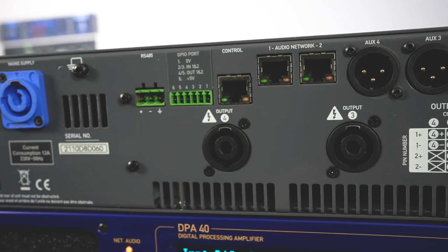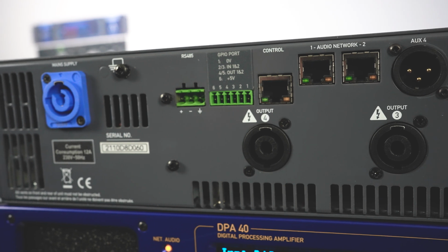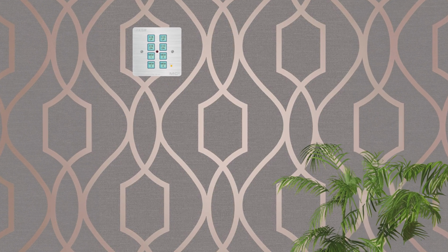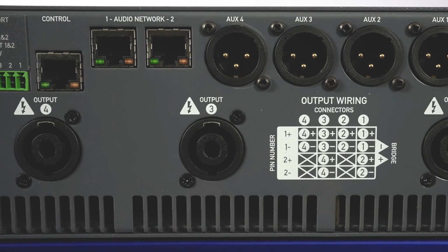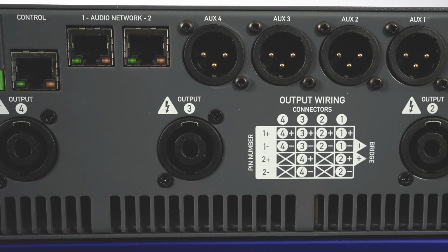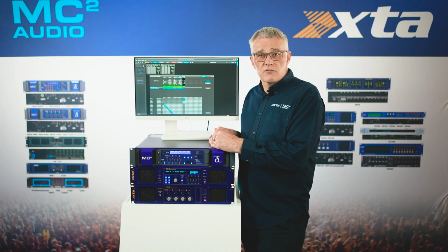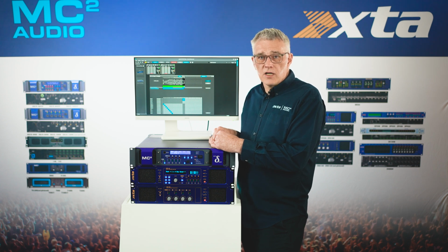GPI for remote control and remote reporting. There is an RS485 connector for connecting to our D-Panel 8 remote. There is a dedicated Ethernet socket for remote control, and there are 2 Ethernet sockets for the optional Dante card. These can be primary and secondary, or 2 ports on a switch. As it is a Brooklyn Dante card, it has AES67 capability.